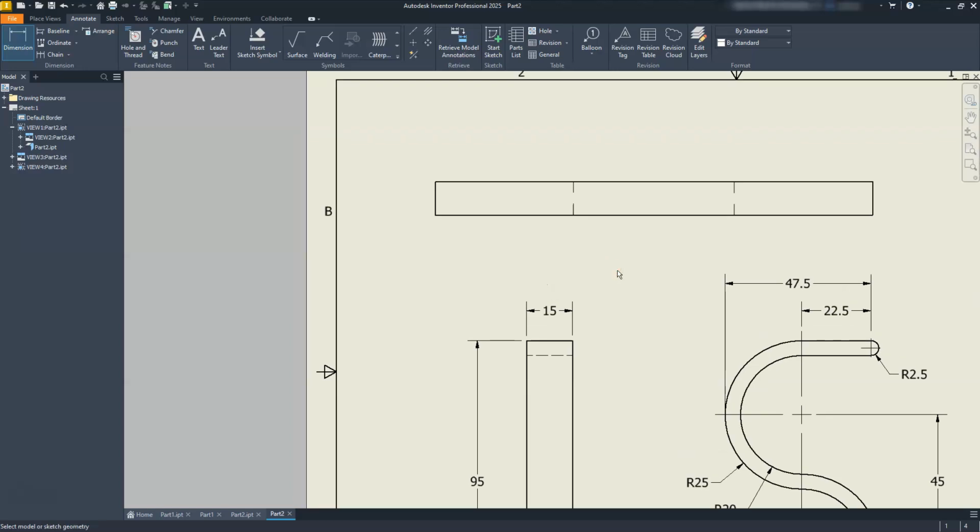And then we can take a look at our flat pattern, right? So we have an overall distance here that goes out to about 189.5 is roughly it. Let's go ahead and place a dimension that tells me where I need to go from when I bend this at.